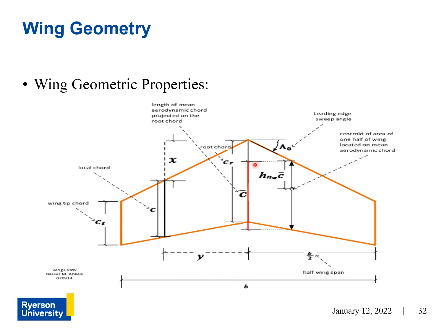That means that the root chord for the reference wing is at the center line of the aircraft and not at the part where the wing connects to the fuselage, if your wing is embedded into your fuselage, as most aircraft are. So the reference wing area is the surface area of the wing. For this reference wing here, the reference area would be this enclosed section.